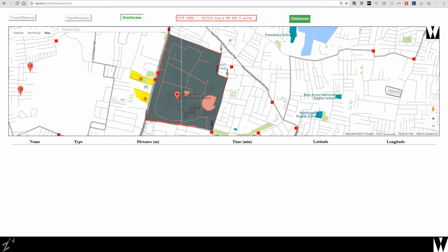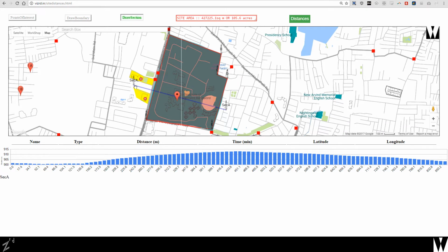And this is our section tool. You just click and it gives you the section along that line. Again, to reiterate this, I've said this many times, but it is important: the scale on the x-axis and the y-axis are not equal. So this is 15 meters, and 15 meters is somewhere there, right? So it should have been actually about half if you were to scale, but I've just fit it into this place. Whichever software you're planning to work with later, you will scale it down so that things actually make sense as a section. For now, this gives you an approximate idea as long as you read the values clean.